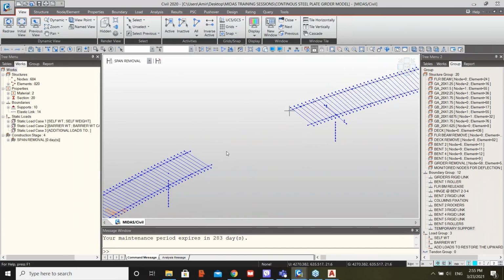And then when you shift to the span removal stage, this is where we are taking out the deck, the demolition of the deck, disassembling or disconnecting all the floor beams in the portion of the girder that needs to be replaced, and disassembling the portion of the plate girder, the left one that had the damage, which was this one here. These are disassembled from the splice to the splice, and the other girder that was not as damaged as the first one as well.